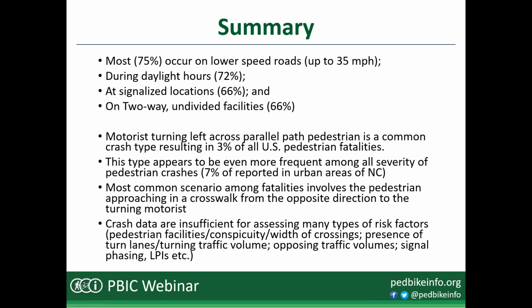So just to summarize, and this is just a really big picture look, because as I mentioned, crash data, the last bullet here, crash data isn't really sufficient for assessing many of these types of risk factors. Such as the facilities present, what was the traffic control operations like? Were there any signal timing strategies in place there? How wide are the crossings? What are the opposing traffic volumes? And so the kinds of gaps that the motorists are dealing with and trying to make left turns. So all of these could come into play in this kind of crash.